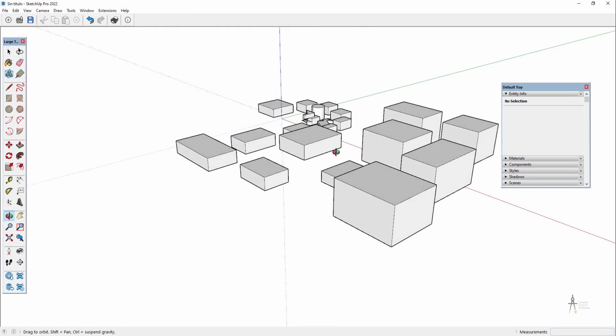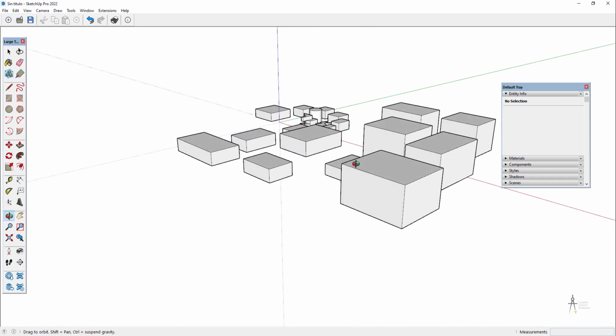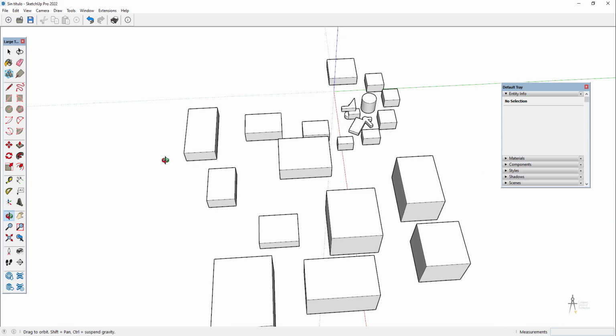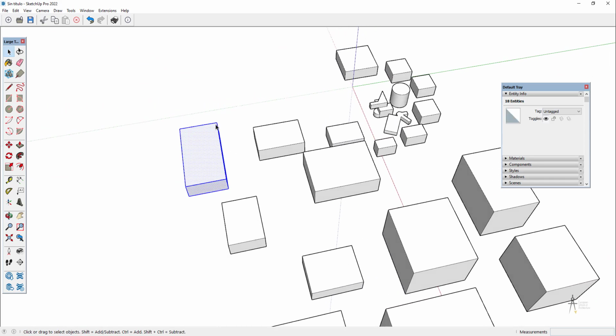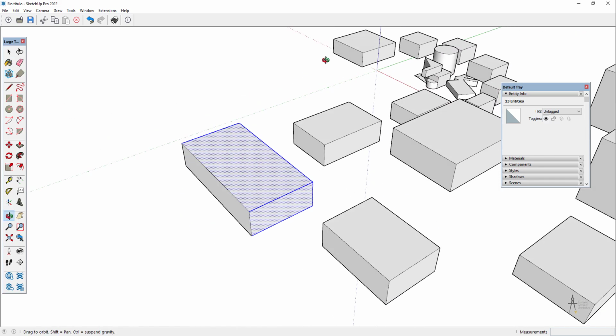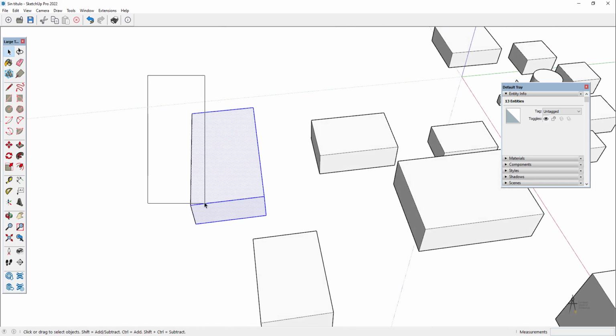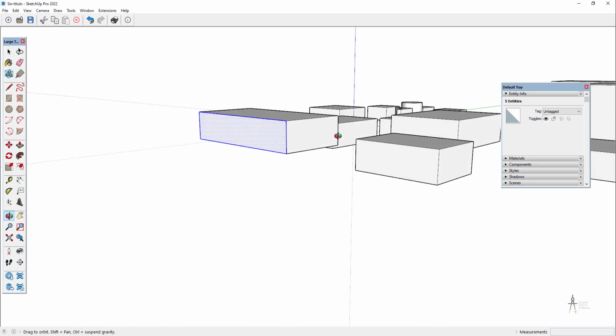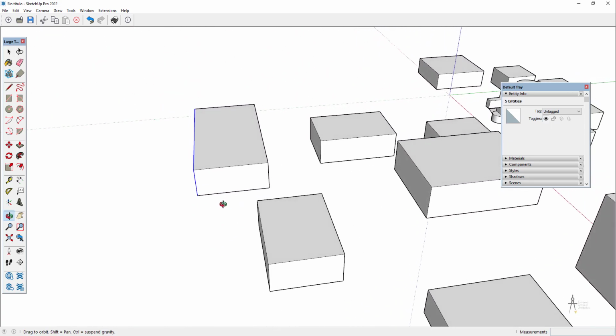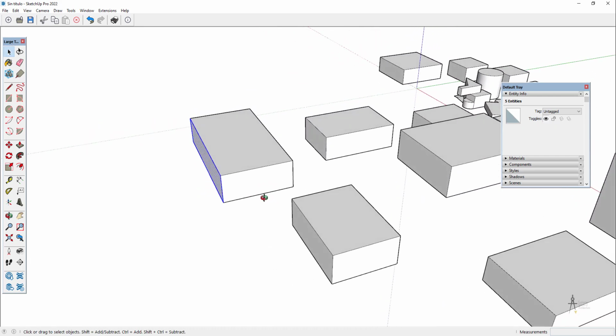You can use a rectangle to select, and if you select from, for example here, from right to left, it will select everything that it touches, okay? What your rectangle touches, okay? So if it touches that rectangle downstairs, it will select it. But if you go from left to right, it only selects what your rectangle covers, okay?